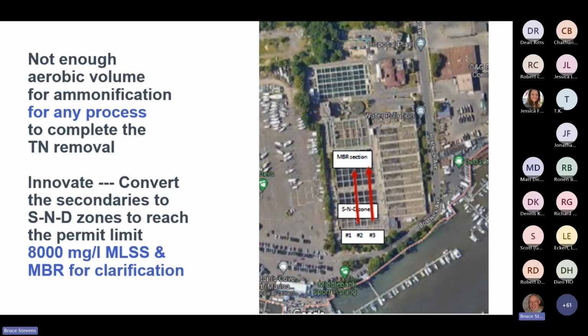It's not magic. That conversion of ammonia to nitrate just takes time, and at these low winter temperatures that we're stuck with, to make the TN removal to get down to less than 5 total nitrogen in the future permit, it's going to be difficult.